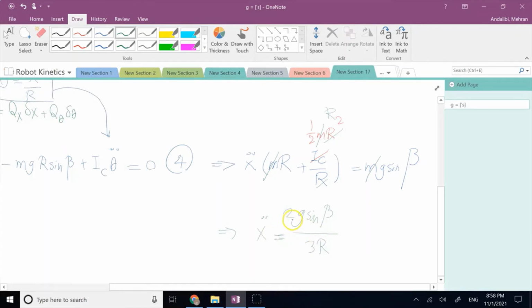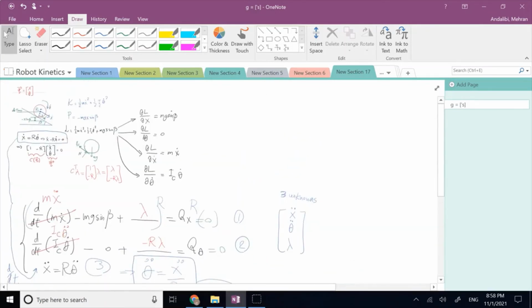This is one of the examples, if you look at my dynamics lectures, that I solved for 2D rigid body kinetics, and I got to this answer exactly. So you see, that gives you the exact same thing as your Newton equations did give you. No difference. And I could easily implement it using Lagrange, Euler-Lagrange equation with constraints. The only thing that I want to emphasize here is this lambda. What is this lambda? If I solve for lambda here, I can get a relation for lambda.